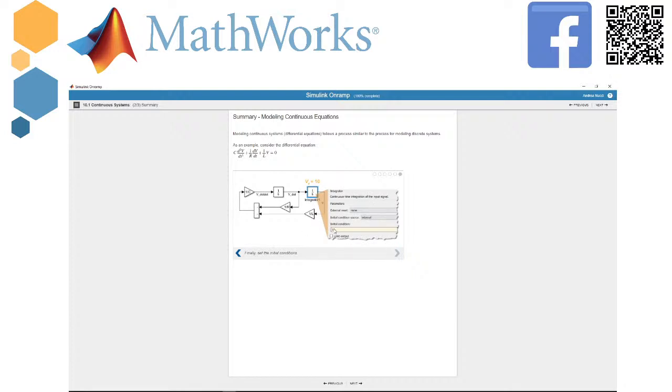And if you want to change the initial condition, as always, you can just double click on the integrator. Of course, you need to understand which integrator you want to change, and it is the one that has the initial condition of the signal you want to study. Okay, so really easy. Calculate the number of differential equations, create as many integrators as the number of derivatives, and then create the whole equation with gains, subtraction, addition, etc. And then you create your system.